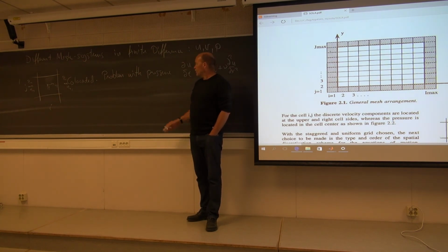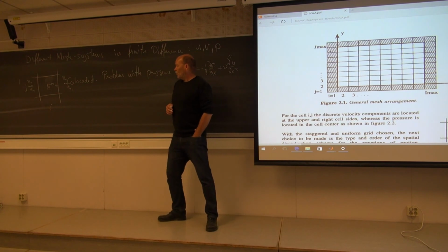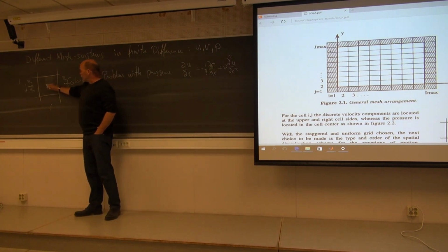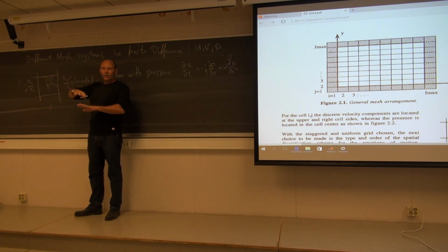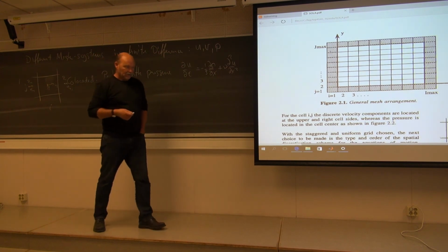So this resulted in very strange pressure solutions. So every other point, like in a checkerboard pattern, can be a totally independent solution to totally different pressure fields, and they didn't talk together. So that was the problem.